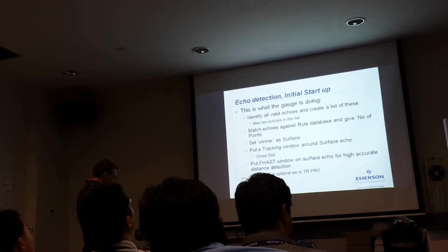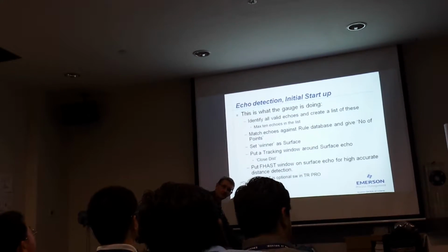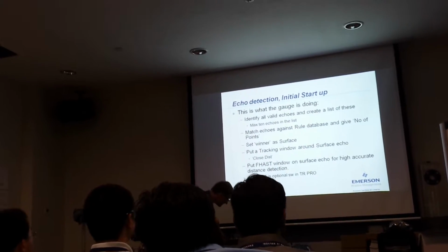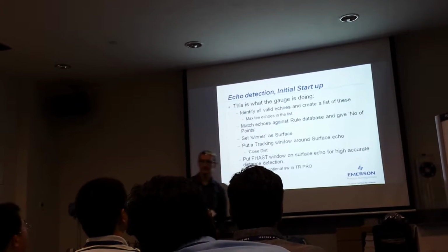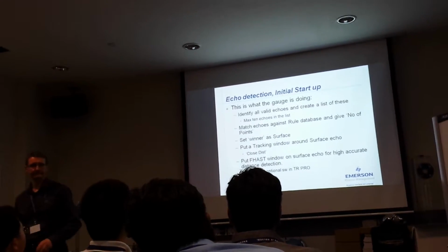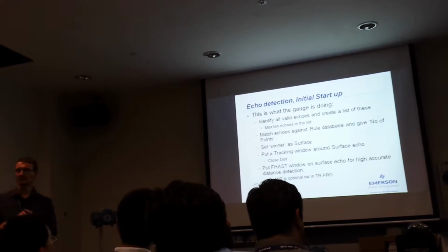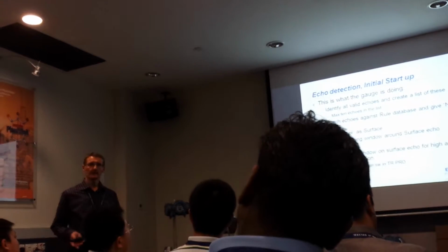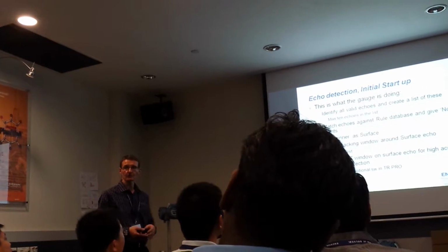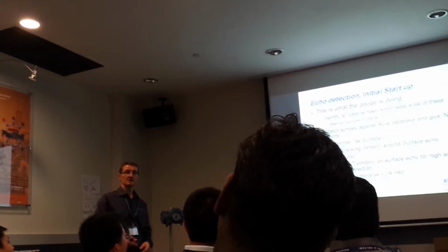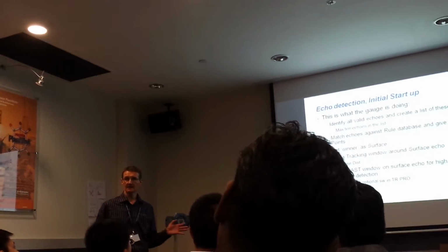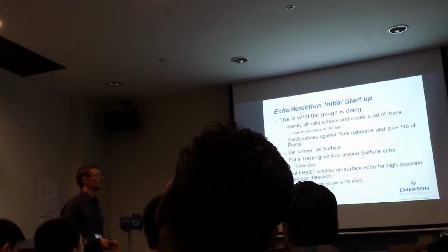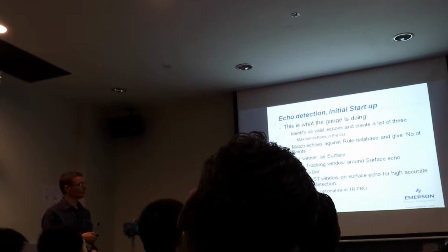Okay, you have the gauge, you have the power supply, and then when you plug it in, like this, then the gauge will start. What happens? You already see we have a boot software, checking the hardware. You say that application is okay. Then it will of course use the FFT, transmit, and see is there any echoes. And then it maybe gets many echoes. So what the firmware has to do now is identify all echoes.